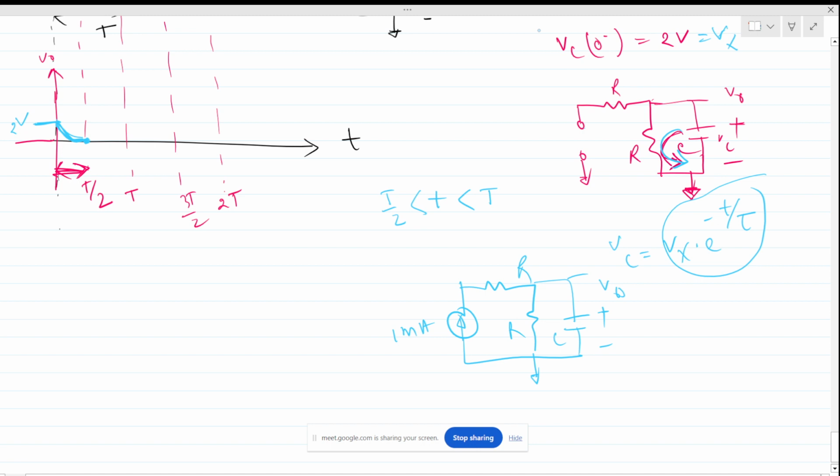So the capacitor will charge again, right, due to this source. Now the question is, what will be the nature of the charging? Is it exponential or linear or sudden, like instant? We all know this will be exponential charging. Why? Because there is a resistance present, so current cannot be infinite, so there cannot be a sudden change across VC.